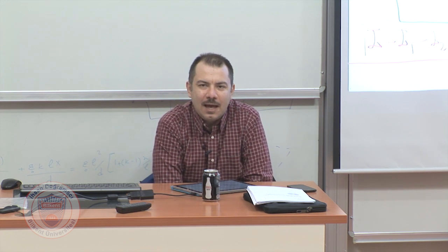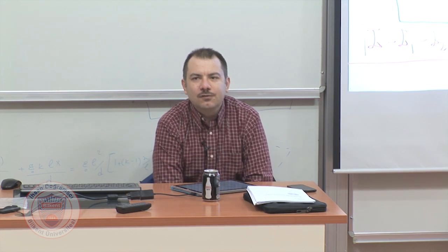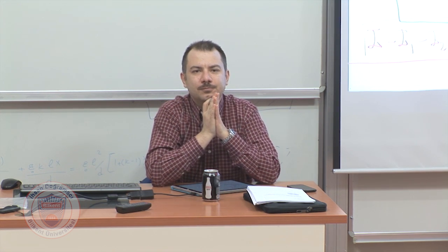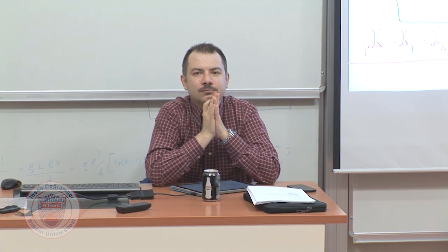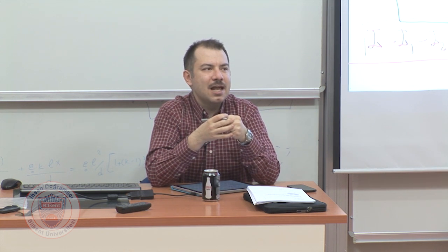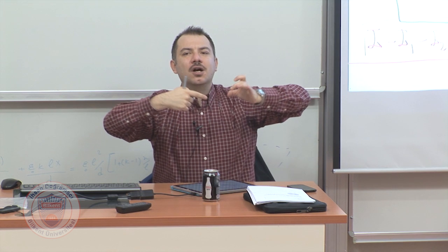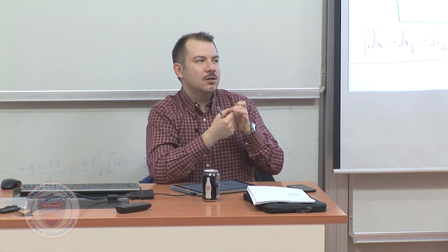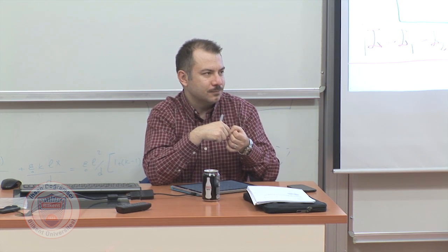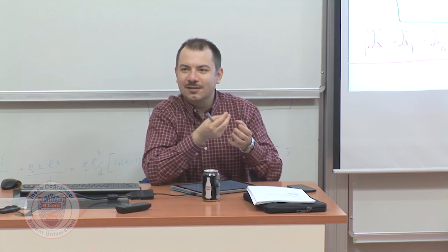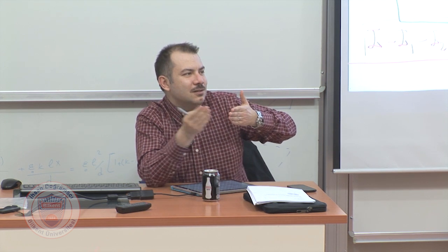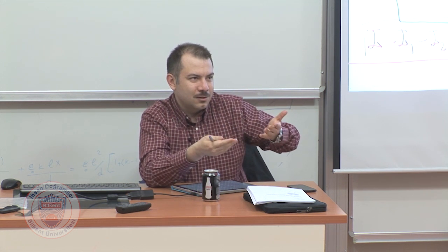Why did I say that? What happens if the total incoming current to any point is not 0? What was current? Charge per unit time. So if I had a node, an element where all the currents coming in added up to some value, charge must accumulate there. I would be constantly adding charge to that point. And I know charge is conserved. It doesn't accumulate at the conductor. Whatever is coming in must leave. That's the requirement for equilibrium.